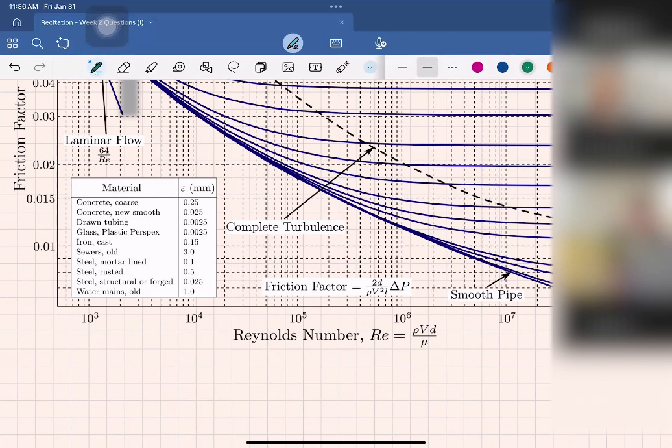Okay, so Reynolds number is around here. Not exactly 2, but it's very close to 2. And for the e over D, we have 0.001, so it should be around here. And now again, we are drawing the curve, and we are drawing this straight line from Reynolds number. Intersection is here.